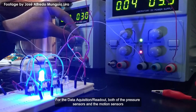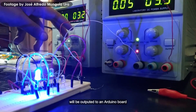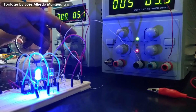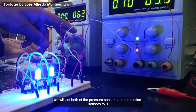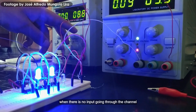For the data acquisition / readout, both the pressure sensors and the motion sensors will be outputted to an Arduino board, where it will light up when it goes over the set value we put it on. For the sensor calibration, so we can find that set point, we will set both the pressure sensors and the motion sensors to 0 when there is no input going through the channel.